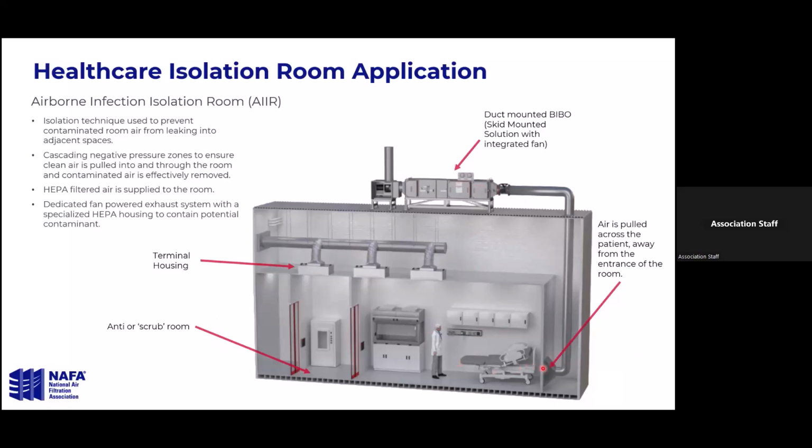And that's an important aspect as well, that you want that air coming over your patient and into this area of the room, instead of your return being over here where the air is being pulled back into this area to be exhausted out. You want that to stay pulling over the patient and out of the room and away from any of the entrances.